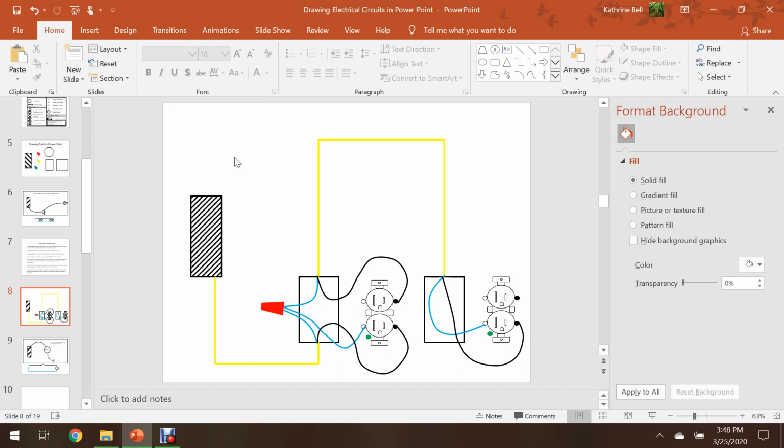The purpose of this is so that in the event of a ground fault, we provide an alternate path back to the neutral conductor or back to the transformer. So a ground fault would use the low resistance of a bare copper grounding conductor or insulated grounding conductor to carry that fault current back through to the grounding bus where the ground is tied to the neutral.